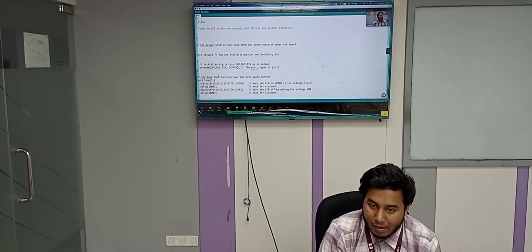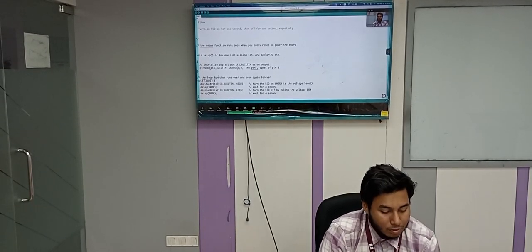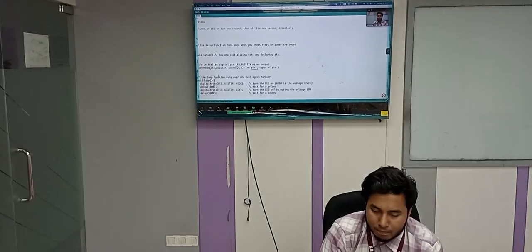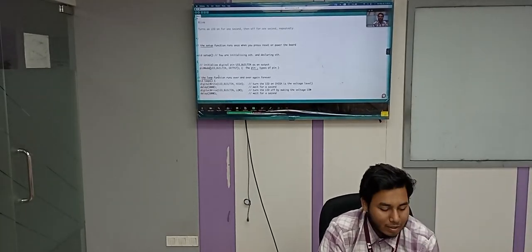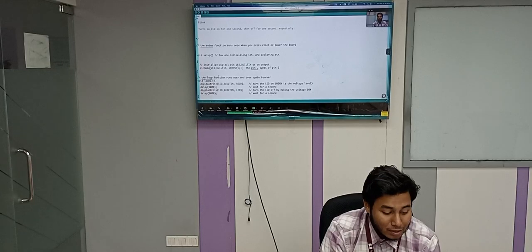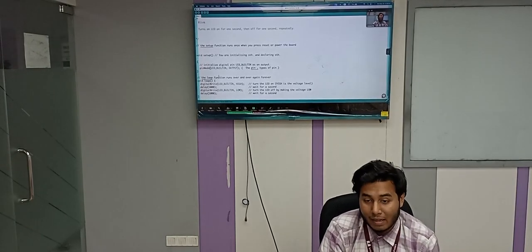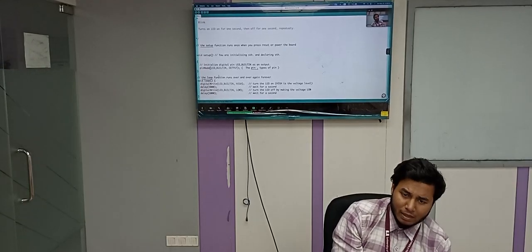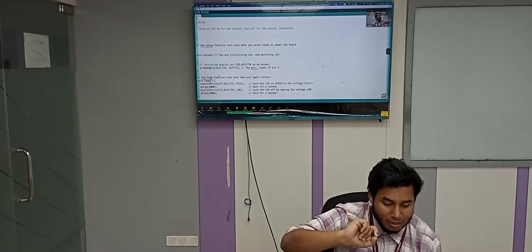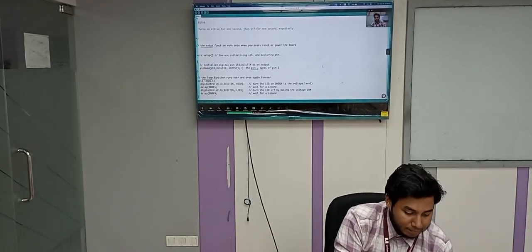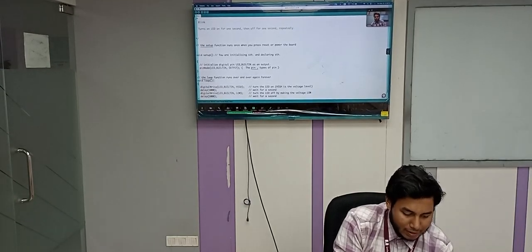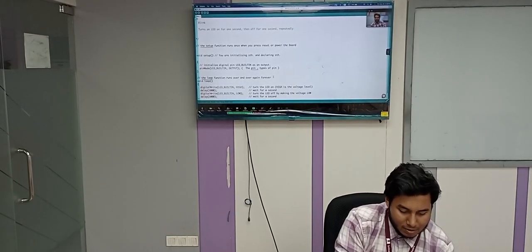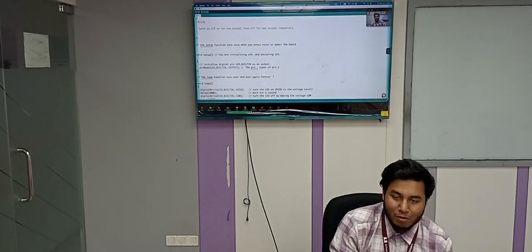Okay, so you have declared the pin, because you are going to have some fun and blinking with the digital pin 13. That's why they have written LED built in. So there's a built-in pin in Arduino just after pin number 13, and that is internally shorted with pin number 13. So that's how much information you get to know about void setup.